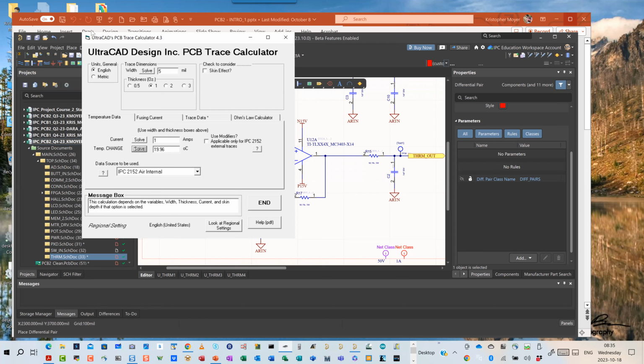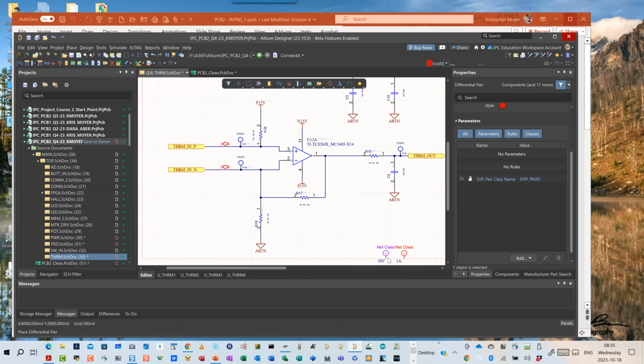And we'll get more into that when we get into manufacturing weeks and so on. But so I basically use 50 volts and 1 amp in my net class definitions here as my intrinsically safe values. And again, more on that as we do our designs here shortly, right? So basically that tool I just showed you, Multiget, it's free now, by the way. I put a link to it on our Edge page to UltraCAD. His tools are all free now, free to anybody.